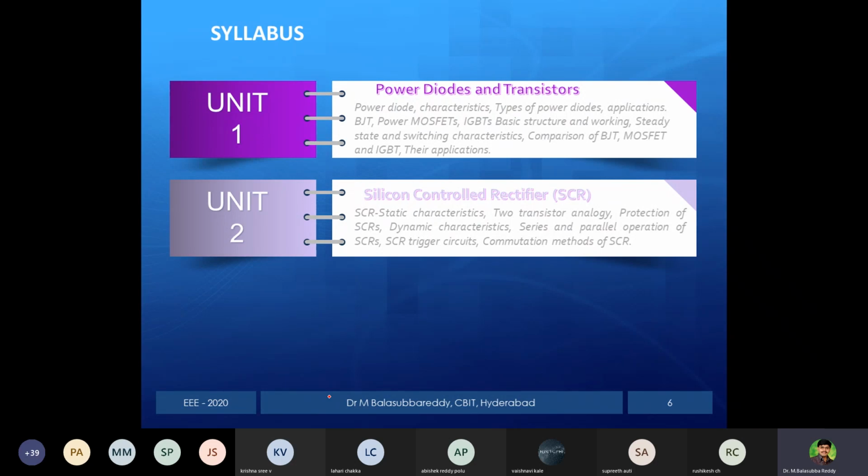I am recapitulating the controllers discussed in the previous slide. The first one is the phase controller. The function of the phase controller is to convert fixed AC to variable DC. That is a phase control rectifier. Which type of commutation is used in this controller? It is natural commutation. The reason is, blindly remember one thing: there are two types of commutation, one is natural, another is forced commutation.